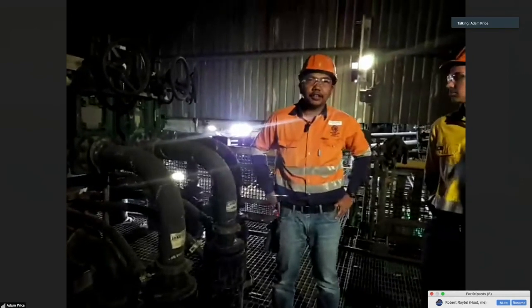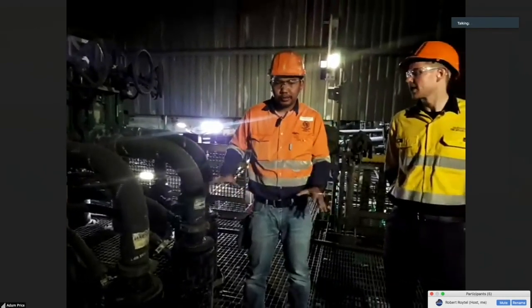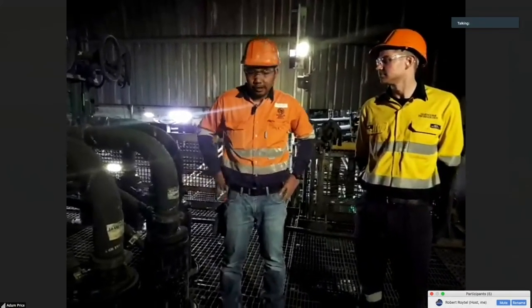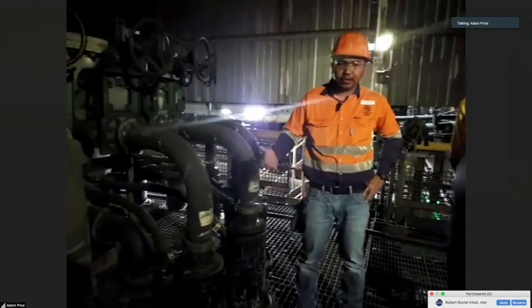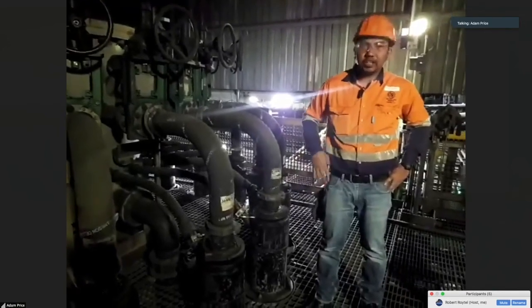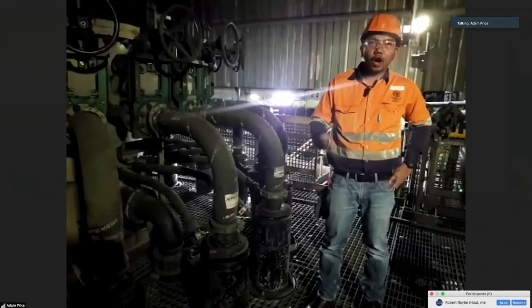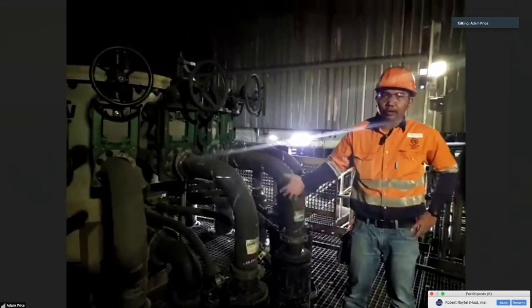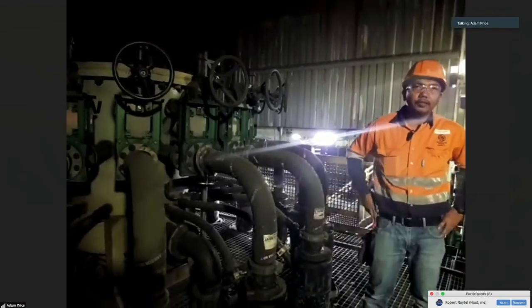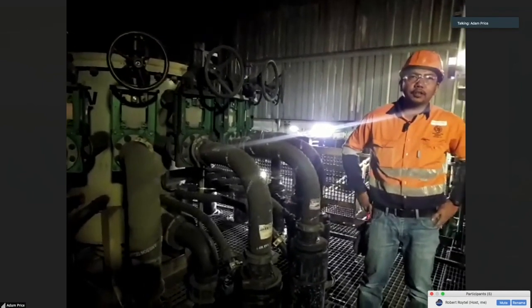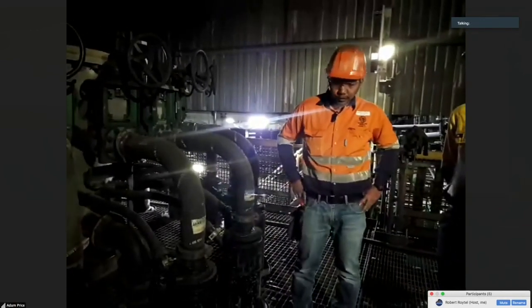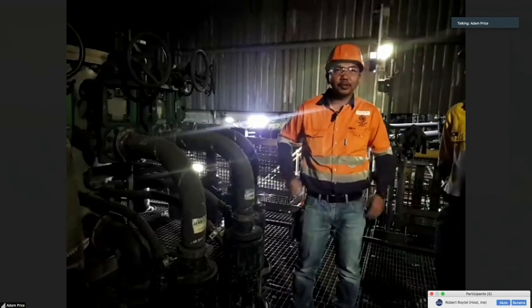Comparing the scheduled maintenance shutdown as well, we make sure that the shutdown is in line with our reline of our SAG mills. So the maintenance needed here during plant shutdown is just checking the pumps, the recirc pumps, checking the ERM valve, and the operators will take the opportunity as well to take a look at each downcomer and the air manifold. So if you come to think of it, there's no contribution of the Jameson cell to the duration of the shutdown.